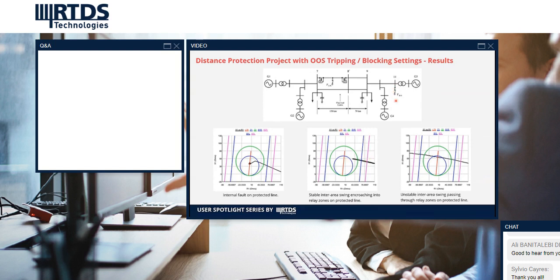And then if you apply that fault at bus 11 for longer, you can cause the system to break apart, where you get the electromechanical swing coming through the zone and then going out the other end. And this is a stable swing and an unstable swing, which the settings can be programmed to respond to appropriately.